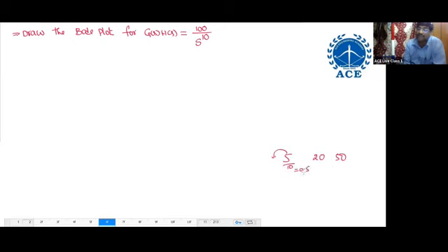But it should not start at 0.5 because the Bode plot is drawn on Semilog sheet. It should start with 0.1 only. You start with 0.1, 1, 10, 0.001, but not 0.2, not 0.5, not 2, not 5. Middle value should not start.